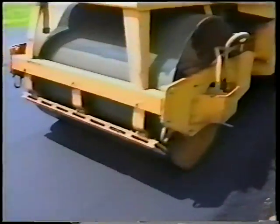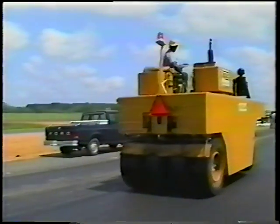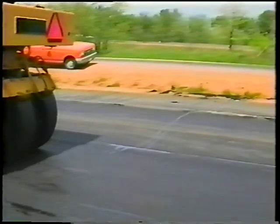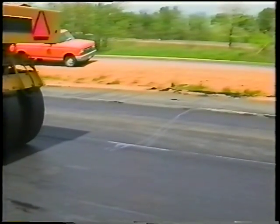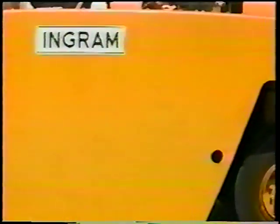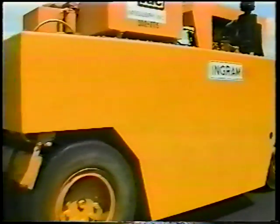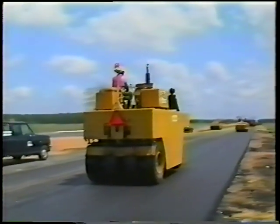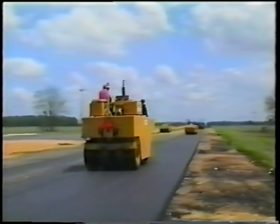Now let's look at the rollers. There are many types, but all can be classified as steel-wheeled or pneumatic tired. For leveling courses, a pneumatic tired roller works best because the kneading action of the tires works the mix into the depressions. Steel wheels, on the other hand, tend to bridge the low spots and not compact the mix as well. All other courses can be rolled with steel-wheeled rollers or a combination of steel-wheeled and pneumatic tired.